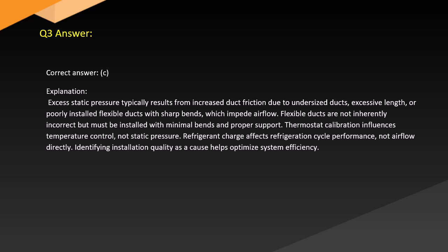Thermostat calibration influences temperature control, not static pressure. Refrigerant charge affects refrigeration cycle performance, not airflow directly. Identifying installation quality as a cause helps optimize system efficiency.